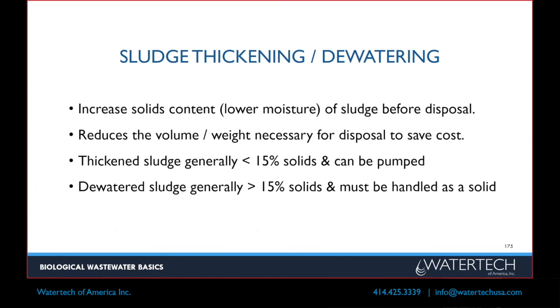So I won't go into too much because Chris talked about it. Typically, the idea between thickened and dewatering is, thickened is typically less than 15% solids, dewatered is greater than 15%. Under 15, it'll be kind of like a cake, like really soft Play-Doh, if you will. It's kind of solid, but you can squeeze lots of water out of it yet. 15% and up, and it's pretty dry. If you squeeze it in your hand, it'll form to your hand and retain its shape. You can stack it pretty high.